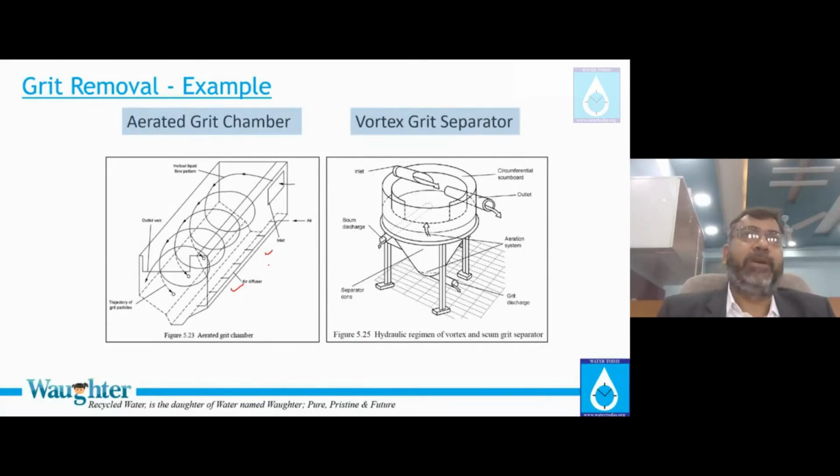What you are looking for in grit removal is for grit to be removed. You do not want grit accumulation. Imagine in this chamber, I'm just trying to show it to you, in this particular area you start filling grit up to here, and then you fill more grit. What will happen is the grit will act more like a sand filter and will start accumulating suspended matter also. Do you like that? No, because the accumulated suspended matter will create a problem of anaerobic degradation right there, a lot of bad smells, a lot of bad things. Therefore you keep even this grit slightly disturbed by doing the aeration.